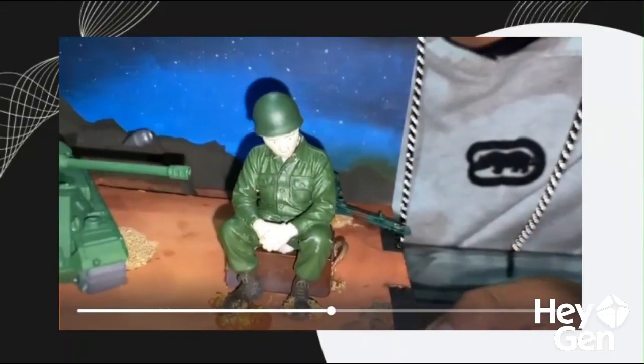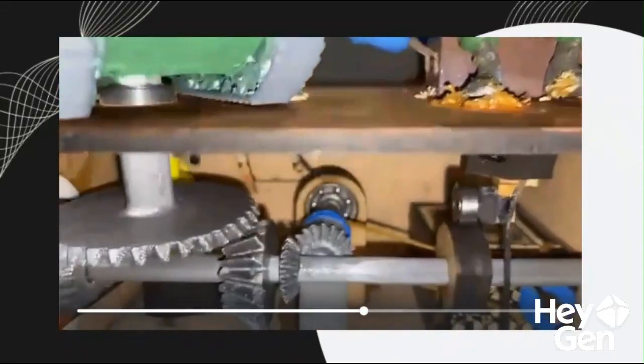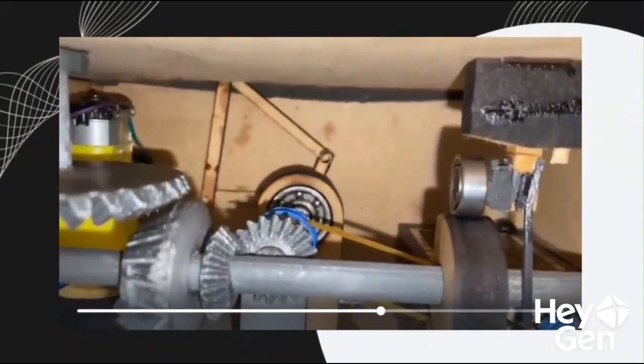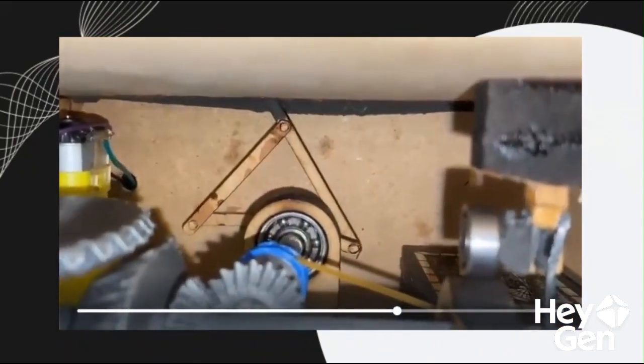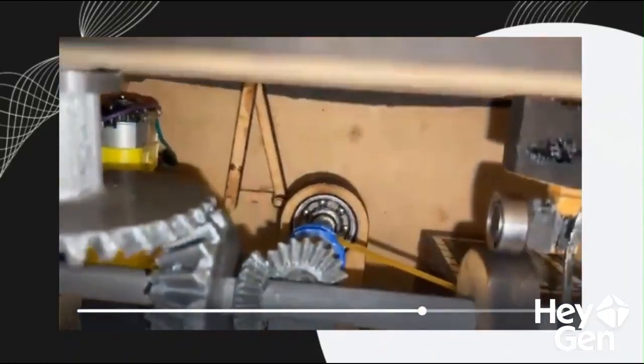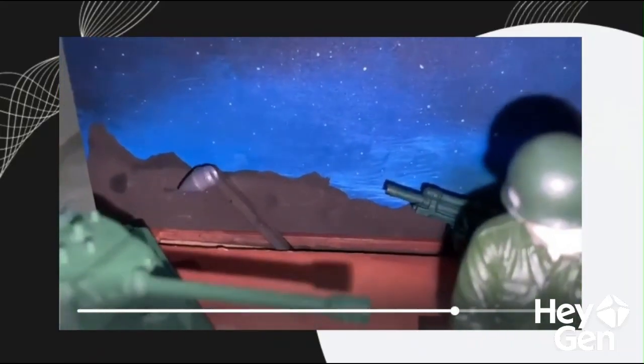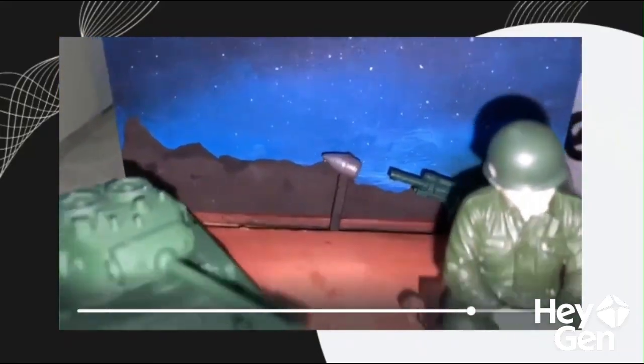Prototype validation. First, on the left side, two bevel gears with teeth on half of their perimeter and offset by 180 degrees move a larger gear connected to the turret, which oscillates between two angular positions. Second, on the right side, a cam converts the rotation into a reciprocating motion, smoothly raising and lowering the soldier's head according to the displacement diagram.